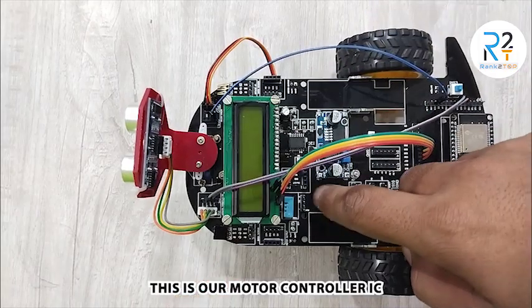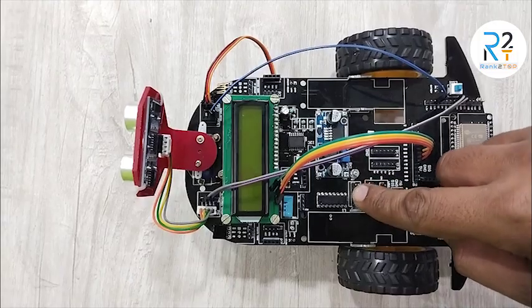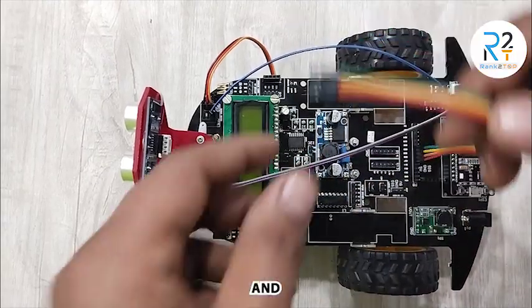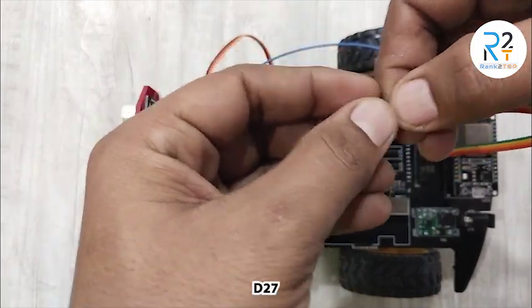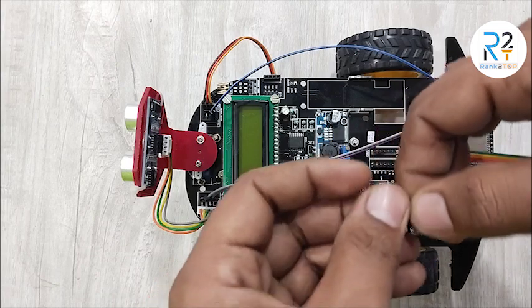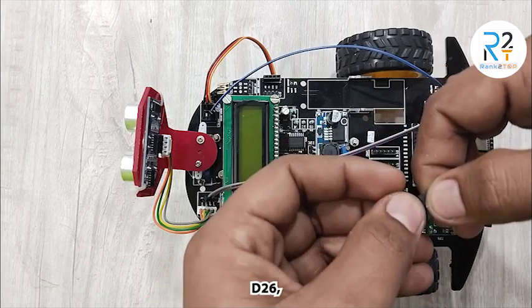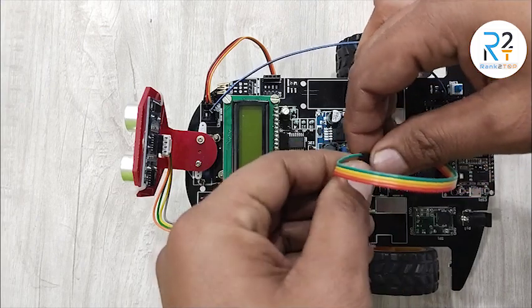This is our motor controller IC and its pins are here. Connect IN1 with D27, IN2 to D26, D25 and then D33.